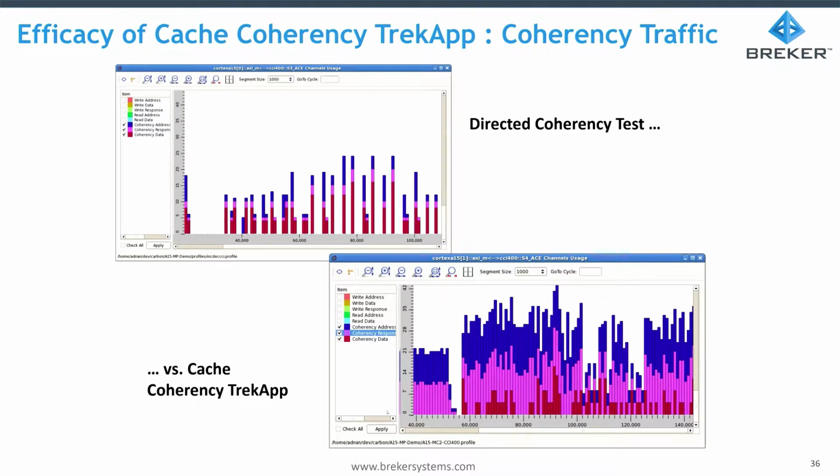But when you compare that to the traffic that comes off of the coherency app, you see that there's a big storm of coherency traffic running around the fabric, which is not completely surprising given the strategy of getting many concurrent coherency scenarios running at the same time that are trying to false share on the same cache line during different states.